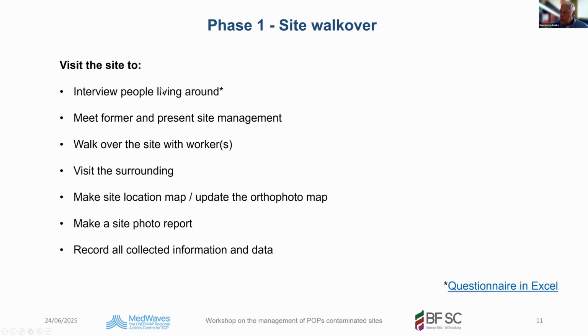Site visit: interview people living around. I have a questionnaire, a standard questionnaire I use, but you can make your own standard checklist for site interviews. You need to meet former and present site management to get information. A site walkover means you visit the site, take enough time, and try to get workers with you to explain what is on site, where they have dumped waste, and where the processes are.